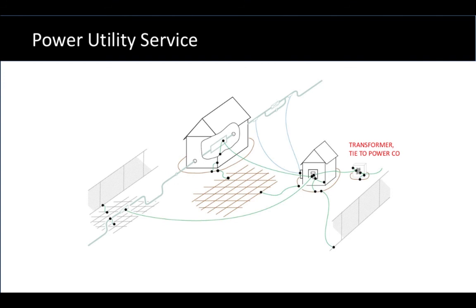There's one last area we need to talk about that can be a bond to grounding systems, and that is a connection to the power company. Now, in our station here that we've been designing all along, if we've done this right, we have not created any inadvertent contacts of the pipeline with cathodic protection to the system or the station grounding system. So we really would not have to address the connection to the utility if we've done all the other things we've talked about. However, let's make this station more complicated.